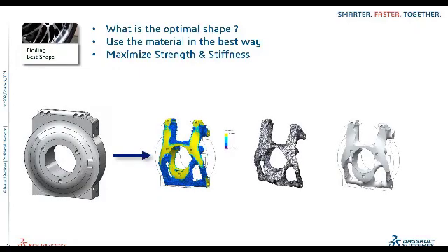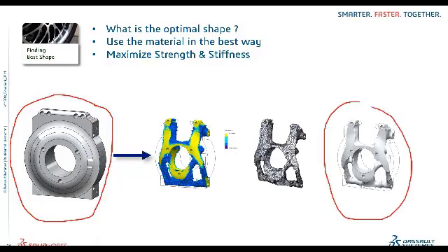This is the topology optimization that our solver supports, where we will be able to design or obtain products that are unimaginable by humans. Right here we can see the initial part, the iterations of topology optimization, and this is what we finally obtained. You can say that this is the same, or in some cases it has better stiffness compared to that of the initial part. This shape optimization is going to be very helpful in the few cases where we have no control over the parameters that need to be addressed.